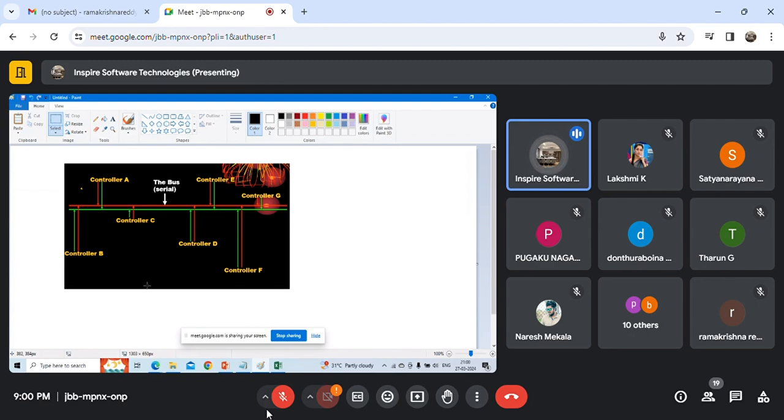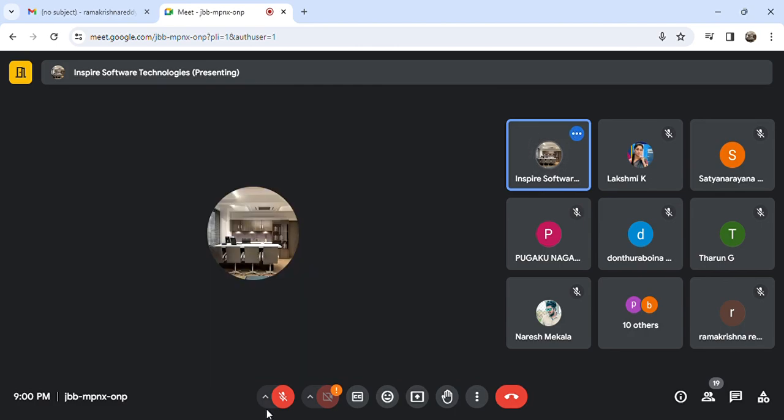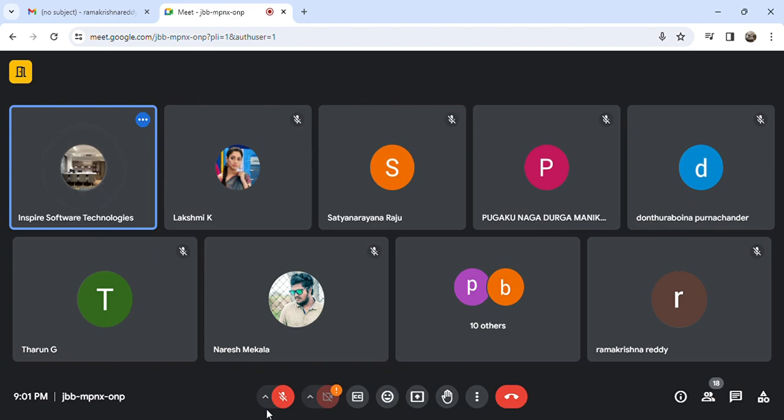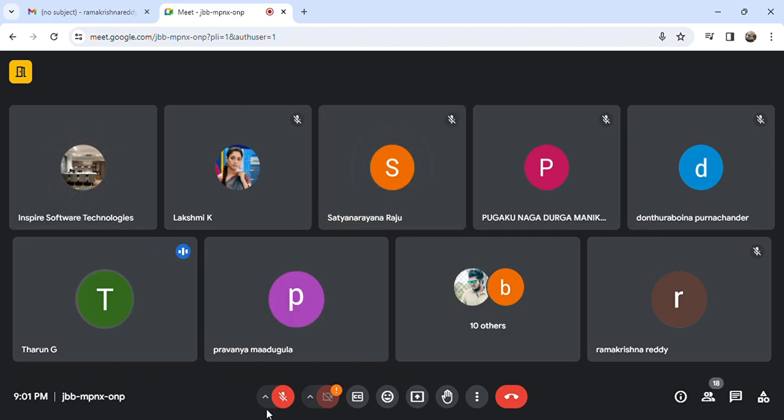Then you can talk about high priority message, low priority message, dominant bit taking the high priority, etc. But the first thing you have to say is that when more than one node wants to send data at the same time, because there is only one single bus, to decide who will own the bus and who has to use it first, we use the CAN arbitration process. Clear? Yes sir. Fine.